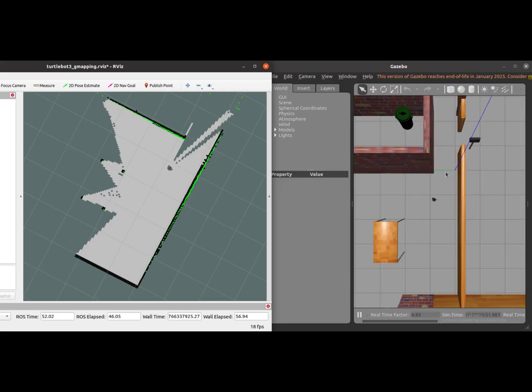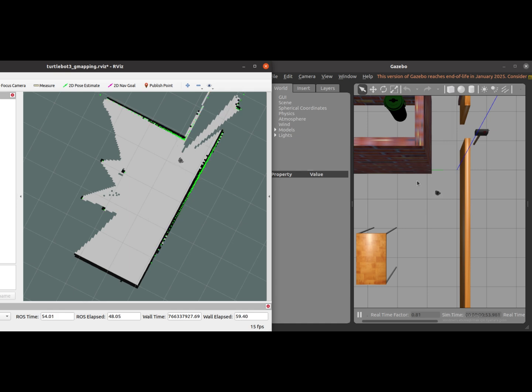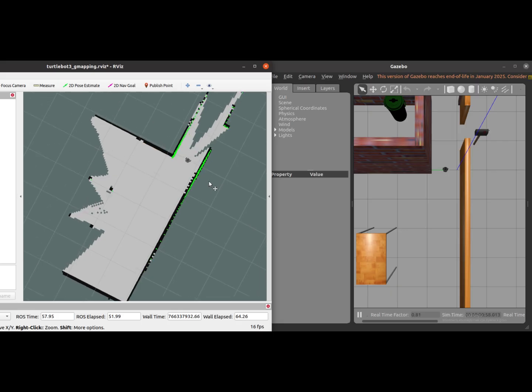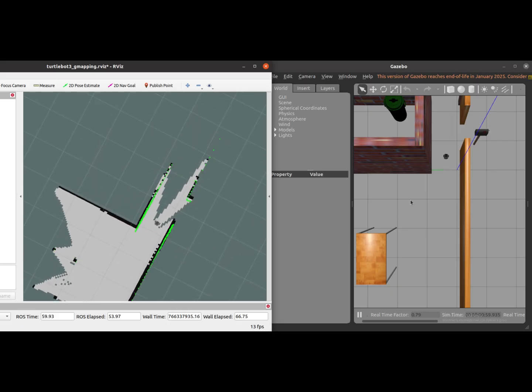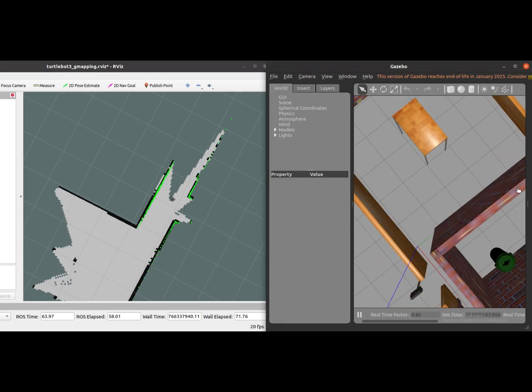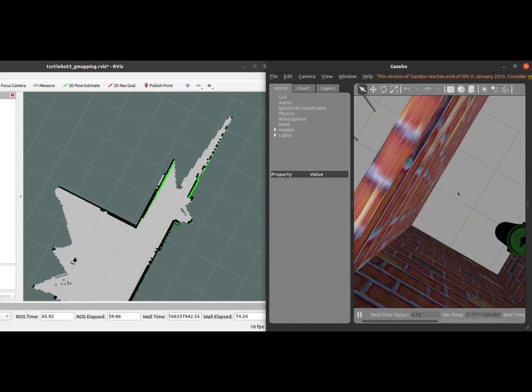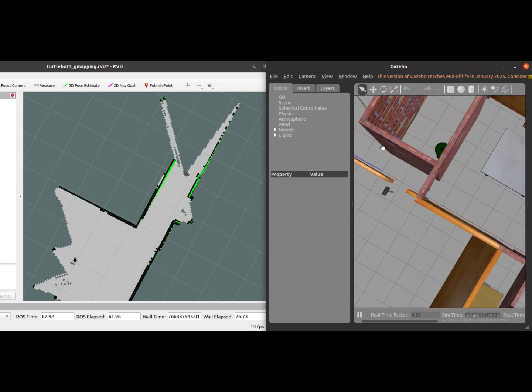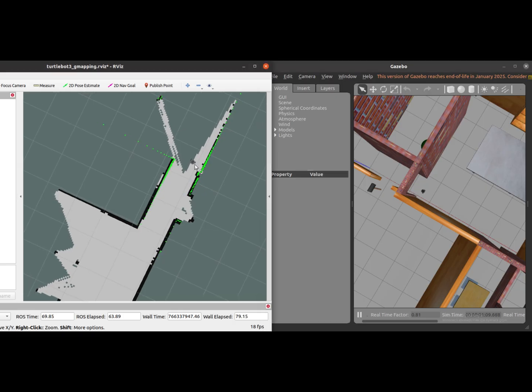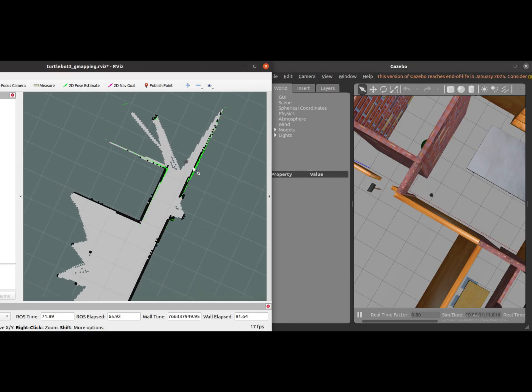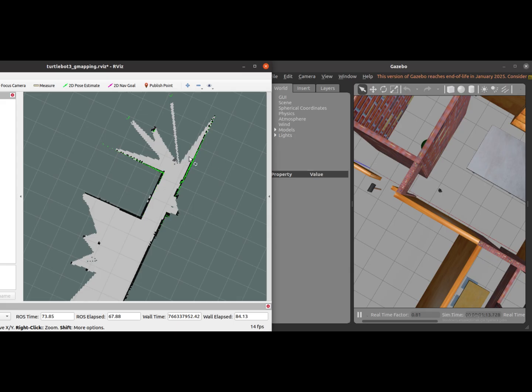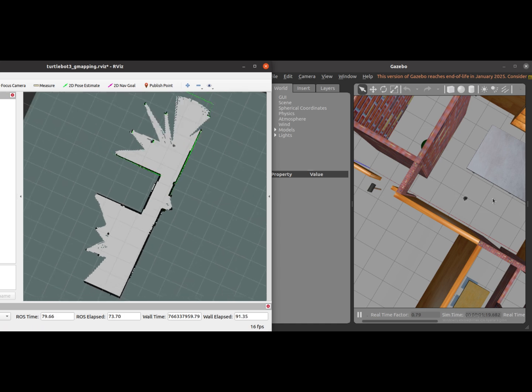During the development, I faced a few challenges. One major issue was the robot sometimes getting stuck in narrow corners or oscillating in the local planner. To solve this, I tuned the move_base parameters, specifically the inflation radius and the cost scaling factor in the global and local costmaps. Additionally, I adjusted the minimum frontier size parameter in the exploration launch file to prevent the robot from chasing very small, insignificant gaps in the map, which improved the overall efficiency.